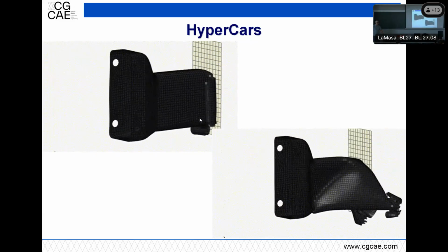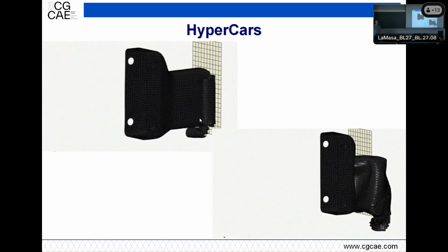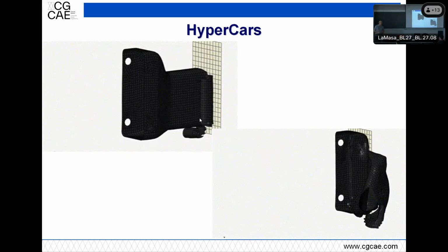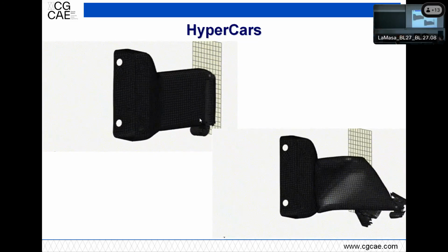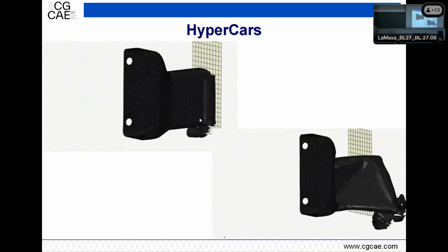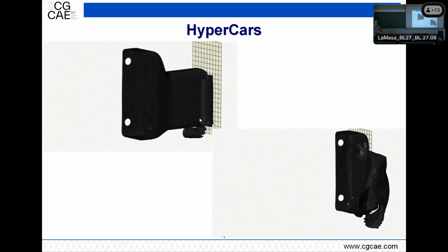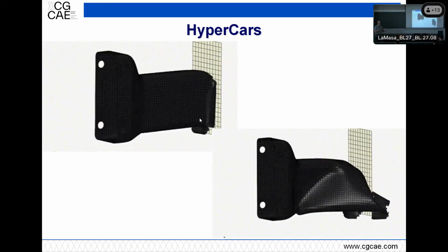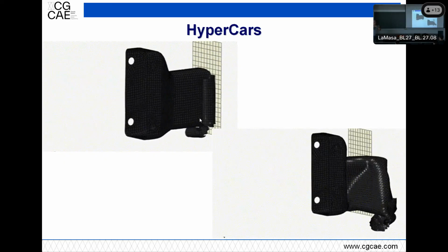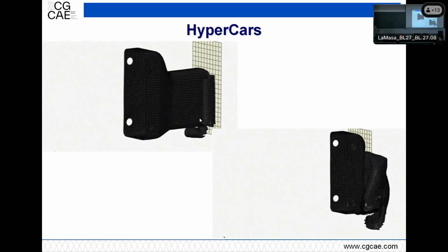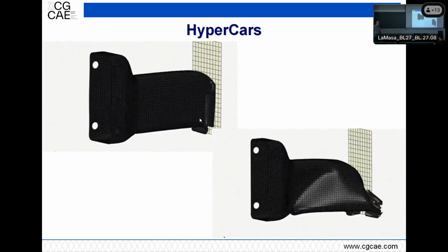From your experience, do you think that rapid prototyping makes the design of components easier or more difficult? In a way that it has to be rapid? It's easier in the sense that you can obtain shapes that you could not achieve in the past. I have an example of that in Toyota. We tried the topological optimizer on a rim, and without thinking that we should have placed some constraint on the topological optimizer, what it built up in the end was something with the spokes which were hollow. And at that time, the rapid prototyping was only plastics. So we could not say, okay, we build it in metal with rapid prototyping.